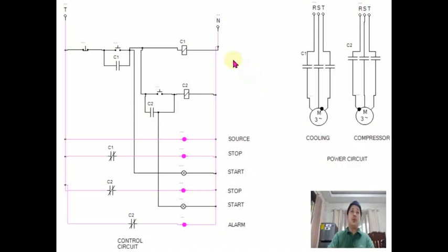This will start because your circuit here, when you start this one, will be closed, allowing the travel of electricity. So I will start your cooling now. As you can see, your blower motor, cooling fan motor, is running because the circuit now is closed.